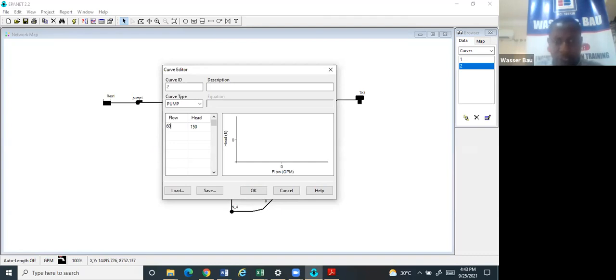And the flow 600. If you go to the markets, I have known this: if you buy a pump, on the body of the pump, it will be written head, flow, head, flow. So if you say you want a pump head of 150, it does not mean it cannot work at 50 head. It can even work at 200 head, but the flow will reduce. They also tell you the best operating efficiency. Mechanical engineers will know this better.